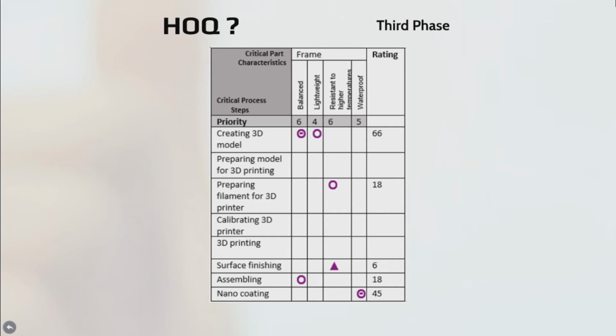This filament is ideal for anyone that desires a structural component with high modulus, excellent surface quality, dimensional stability, lightweight, and easy of printing. Lightweight plays a crucial role in our design, but also it results in more wear on your nozzle. So we are going to switch from brass nozzle to stainless steel one. Also, carbon fiber is resistant to much higher temperatures comparing to PLA and ABS and the other filaments.